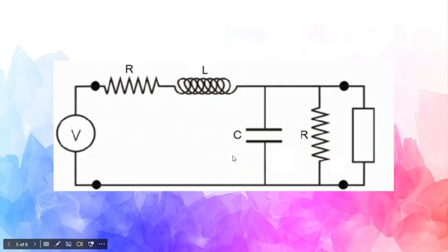Well, when I was studying this stuff, there was a confusion. Okay, fine. Mathematically, that is fine, but what it is actually, what it is physically. Any electrical circuit can be comprised of three things: resistance, inductance, and capacitance. These three things represent any electrical circuit. When current is passing through this resistance, it gives I square R. That energy can be converted into heat, can move something, like when we are giving supply to a motor, it rotates. That's an energy, that's active power.